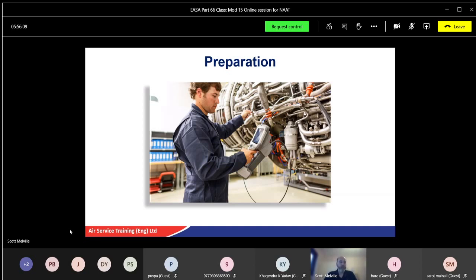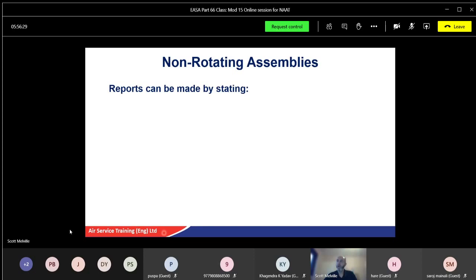Endoscope equipment contamination. Don't get any fuel or oils on it. Watch for electrical potential difference between the light source, aircraft structure, fuel, and all of this. Now, saying that, they're all battery pack operated. They do get mains ones that must be used with a flame-proof power source as well. So if they're non-rotating assemblies, things that are fixed, you can use access ports.